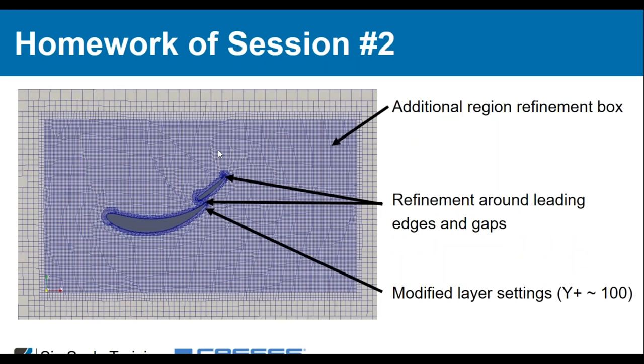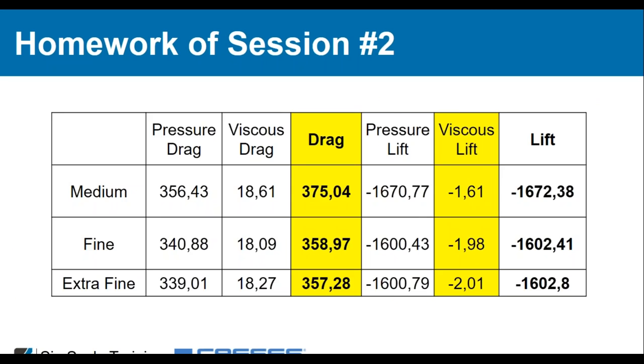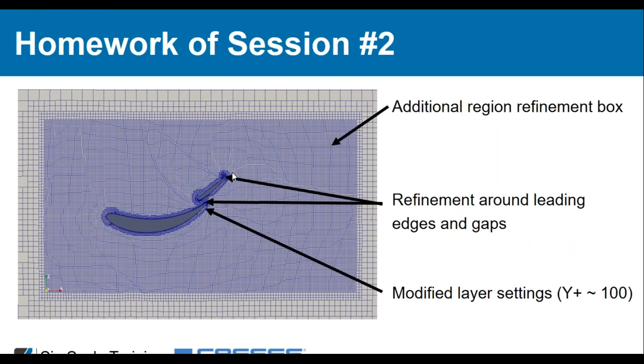And just because I think some of you are interested, I've prepared some screenshots of this run, which we call dextrafine. First of all, you can see a slice through the mesh. This is a symmetry plane, which is called bounding box 1 in our simulation project. And here, for example, you can see some first changes I made. First of all, I added additional region refinement.